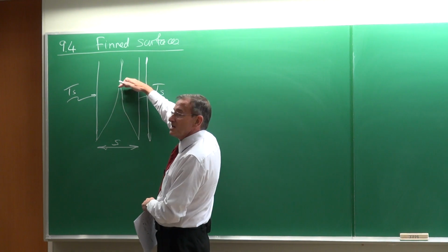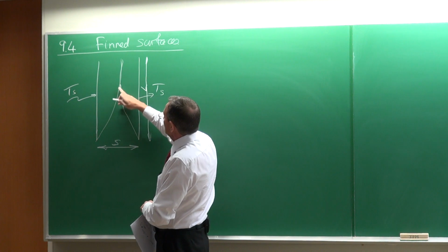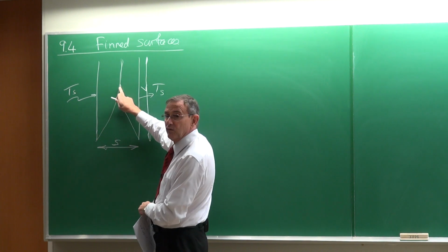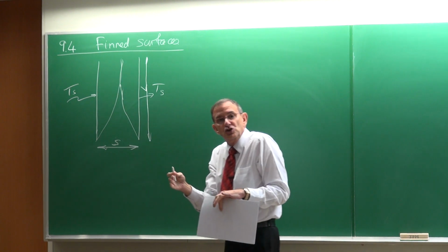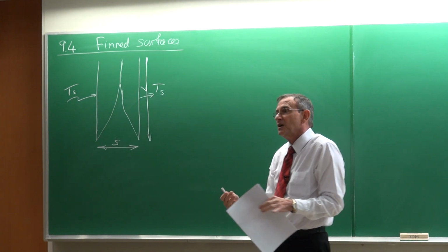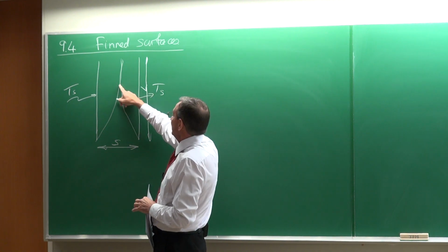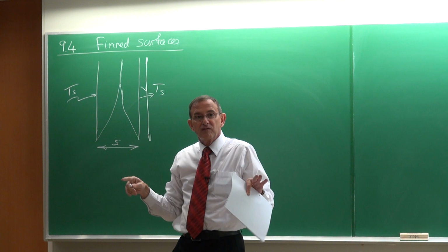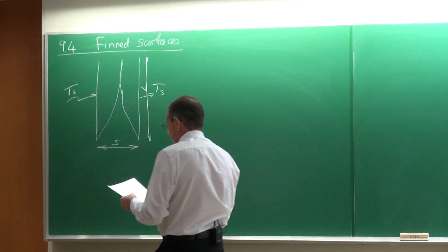In many cases, the designs are actually to optimize your design. You will actually go and determine how long it will take before the flow is fully developed, and then that would be the length that you're going to choose typically in your design. Why? Because the heat transfer coefficients here are very, very high, but from that point onwards, when the flow is fully developed, the heat transfer coefficients are much lower.